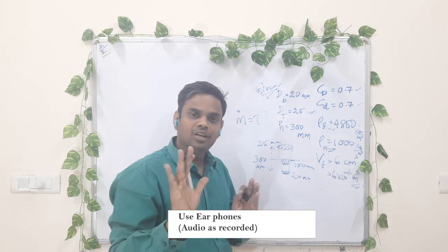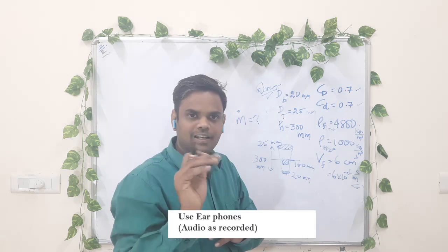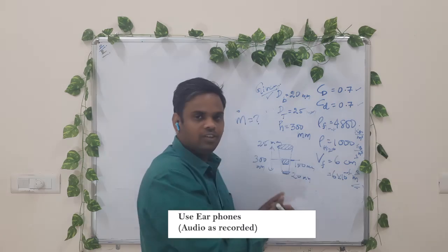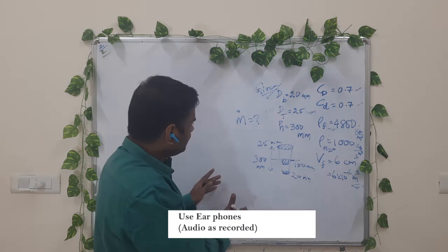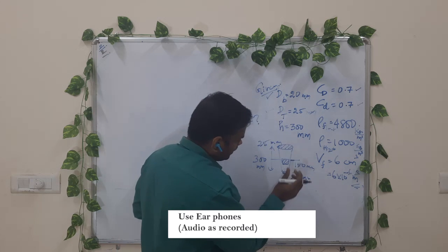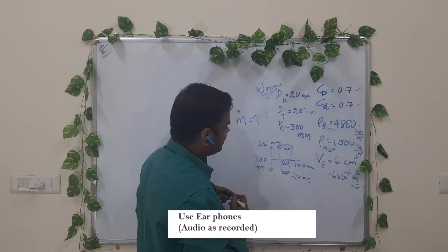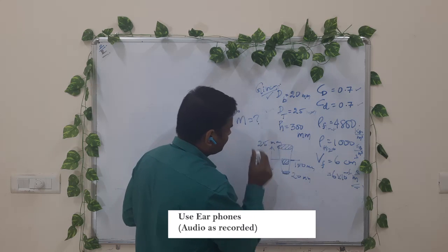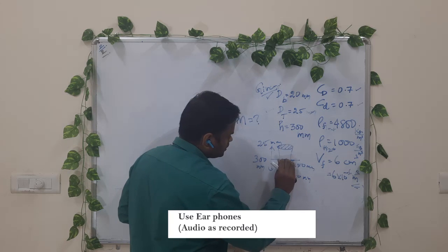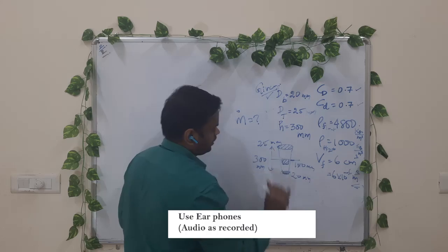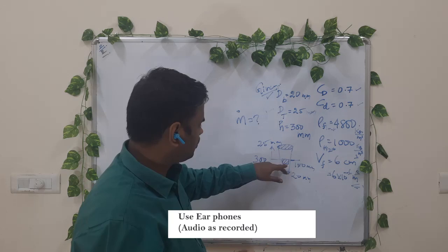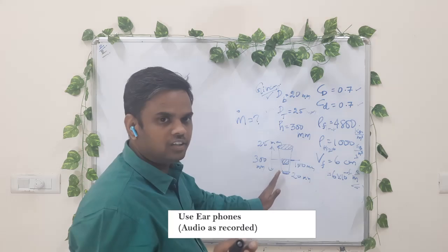Remember, in actual equipment there will be a calibrated scale. Directly we are going to get the volumetric flow rate. Now, just to understand the derivation that we have done, we are solving this numerical. Here I repeat, what is given is a rotameter of 300 mm height, with a bottom diameter of 20 mm and a top diameter of 25 mm. The question is, determine the mass flow rate when the float is in the middle of the rotameter, or the float is at its half height.